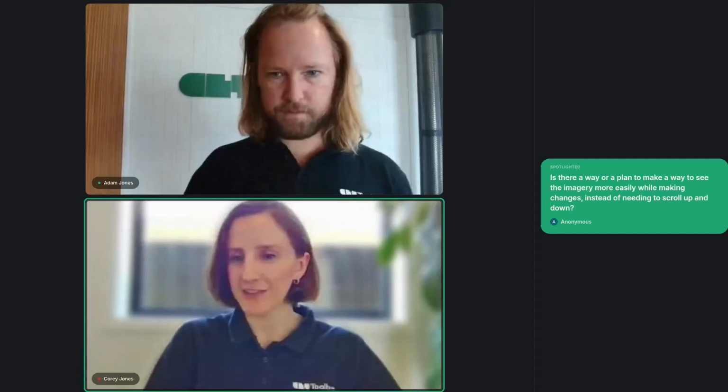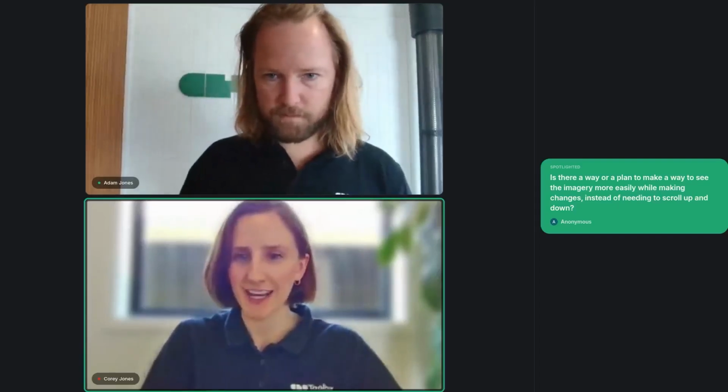Awesome question. And we'll have time for a couple more, so pop them in the chat if you have any. Otherwise, there's two remaining. We have one that's, what about the ability for multiple plates and moment connections in design? Yeah, it's also a really good question. So that is the next iteration of our Dowel calculators. At the moment, you've got 17 scenarios, like I mentioned before, internal plates, external plates, all simple connections, but we are grouping it into one, stacking them on top of each other for powerful Dowel calculators where you can add moments. And yeah, this is pretty late stage development as well.